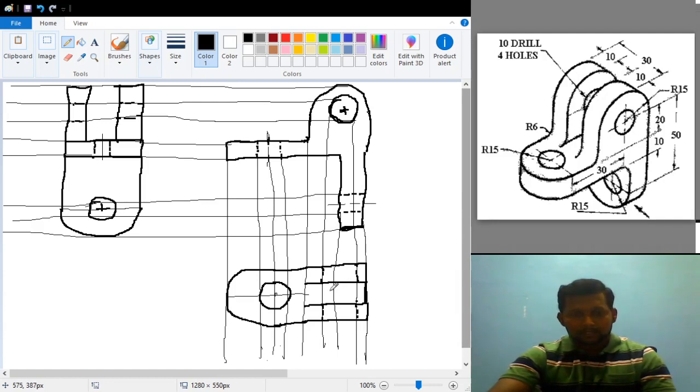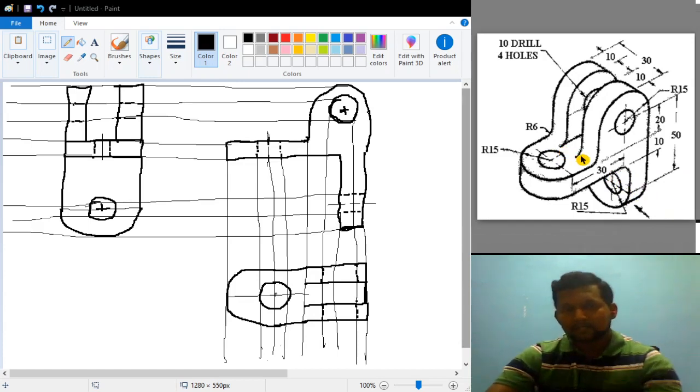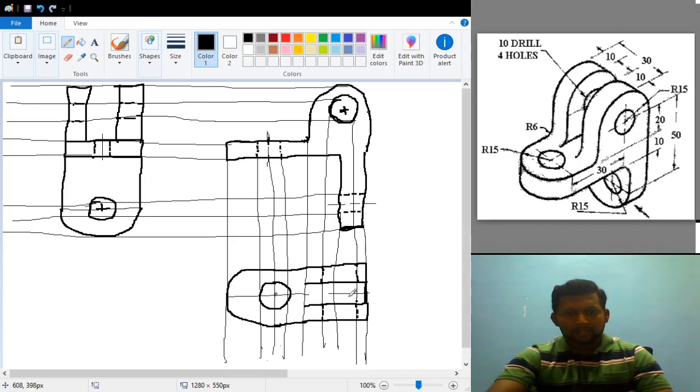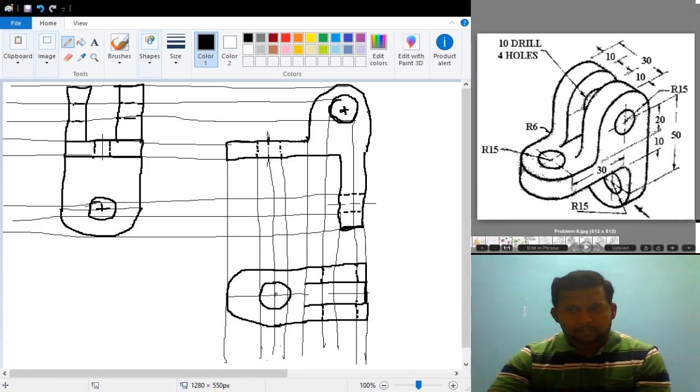And coming to the dotted line for this particular circle in the top view, when you are seeing from the top, how much is this particular complete distance? This particular complete distance is equal to 30 mm. I mean I am talking about the breadth. So the breadth is totally 30 mm. In that 30 mm, for the 10 mm block, we have the dotted lines with a distance of how much? 10 mm. So I will just try to draw a construction line over here. With a distance of 10 mm, this particular circle, since it is 10 mm and this total distance is 15.